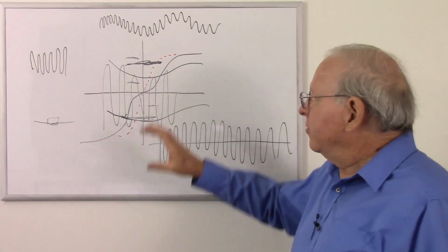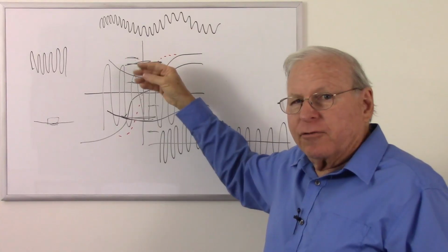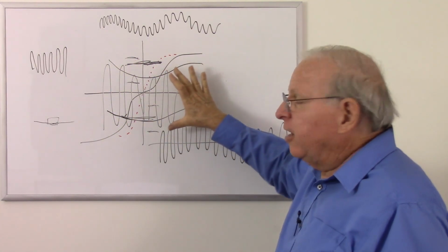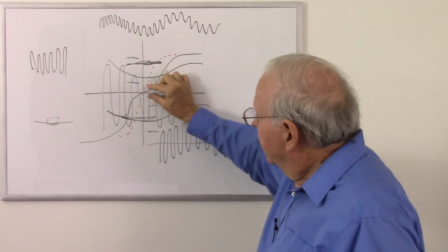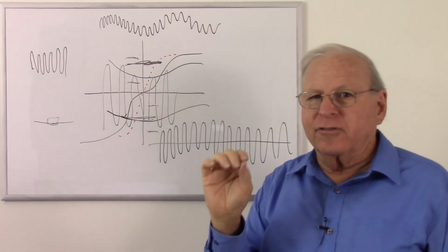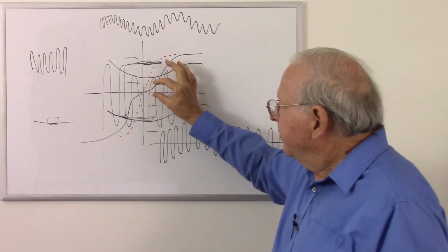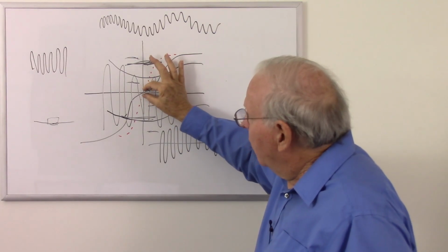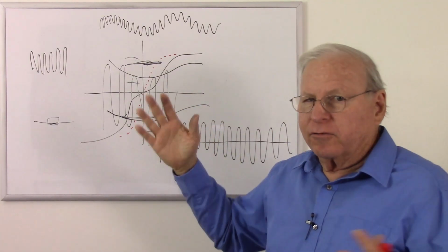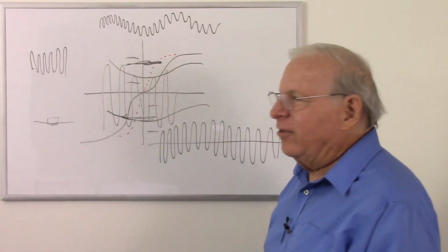Remember DC bias, we just kept it up in here, but because we had that tape strongly magnetized, those domains were going by making a hissing sound. Now we're still going to get that hissing when we have a strong signal, but if we have a weak signal, we're not going to be magnetizing them as strongly, and so we don't get that hiss because it's the strongly magnetized domains going by the head that cause that hissing sound. So when the music is quiet, the domains are not as strongly magnetized, and so we don't hear the hiss. And of course, when the music's loud, it overwhelms the hiss anyway. So that's the purpose of the AC bias.